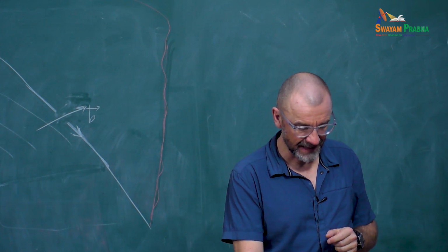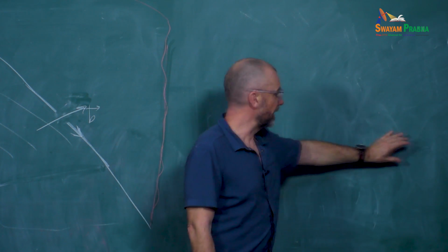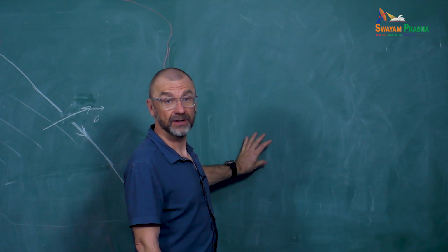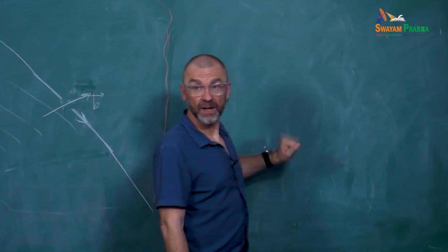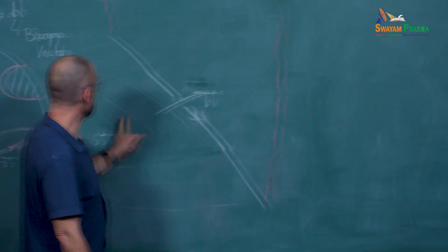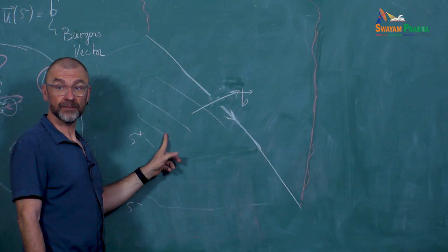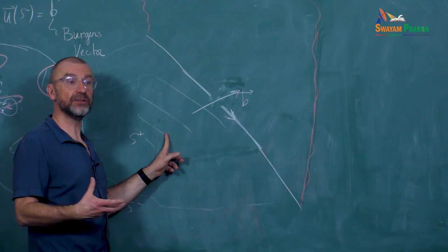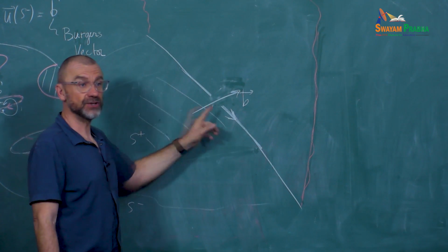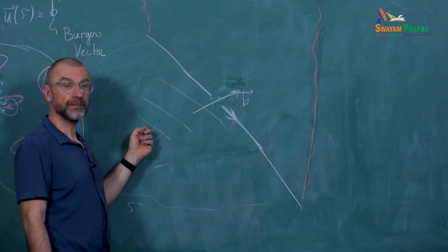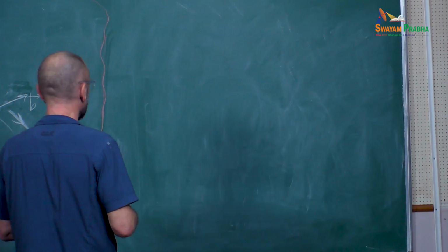Okay, now, here we finished the last lecture by writing Navier's equation in terms of displacement field. Well, actually, you can solve the Navier equation with a boundary condition, which is a discontinuity of displacement along a surface. And then you can get an analytical solution for what is the displacement field around the dislocation due to this discontinuity. And the simplest expression is the one which is written here. It's for the screw dislocation.